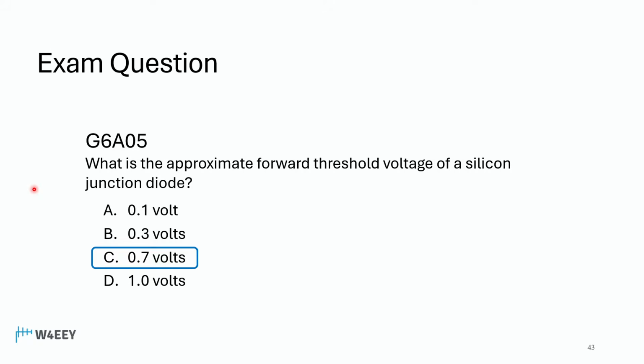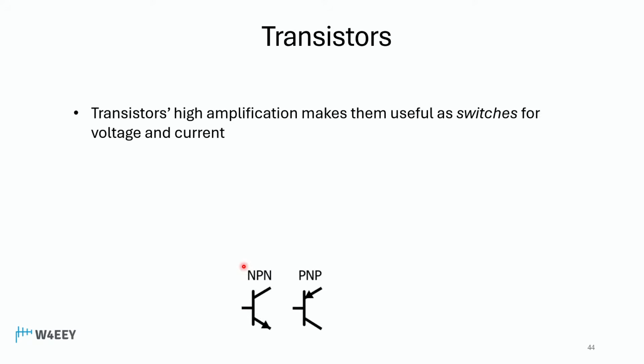These can be good troubleshooting aids too, because if you're working on a circuit and you don't know if it's working properly, if you measure the voltage across a diode or a PN junction in a transistor, you would expect it to be about 7/10 of a volt if it was forward biased. If it's 0, it means probably the part is shorted out, or if it's something else, probably something wrong in the circuit. So these are useful numbers.